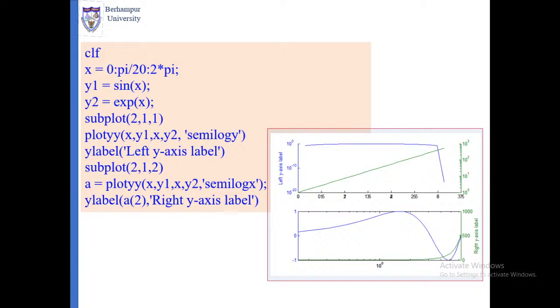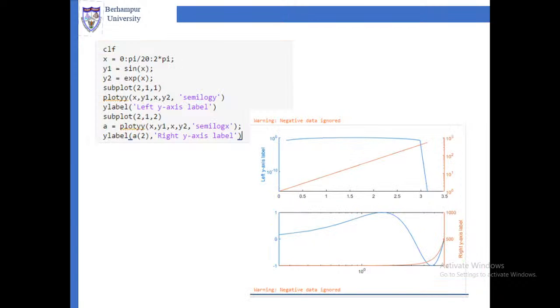Then x is equal to pi, same plot. You can use semilog here. We are using semilog here. You can use loglog, semilogy, semilogx. Using those plots, we are again plotting the plots. So if in linear plots something is invisible, you can use semilog plots. Both of them are visible in the top as well as in the bottom. Okay. This is the repetition of the previous one. The only thing is, it is a snapshot from a real Matlab window.